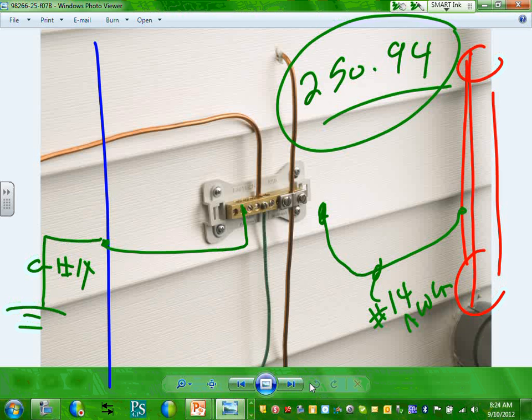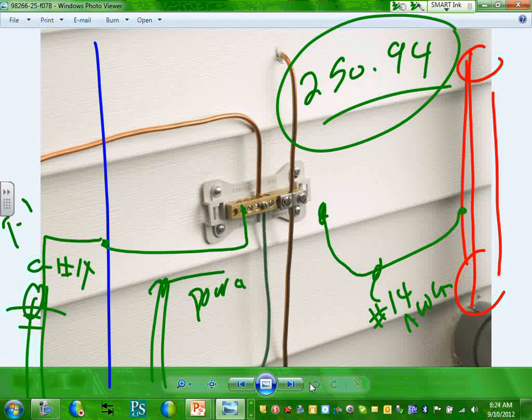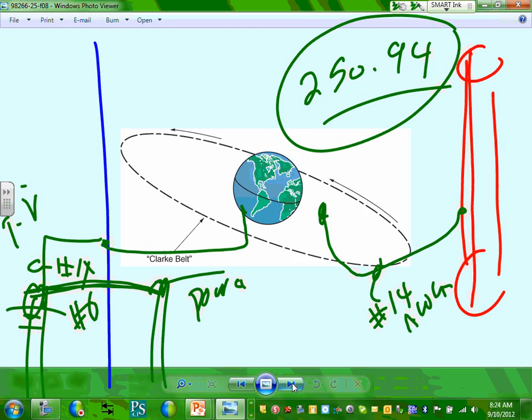We'll talk about grounding. So if I have 2 ground rods, one here and one here, this is for the power, and this is for the TV. What do you need to do? The code requires you to bond these 2 together, typically with number 6. Like you're looking at it right here, you bond these 2 ground rods together. Okay, so that's basically what you need to do.